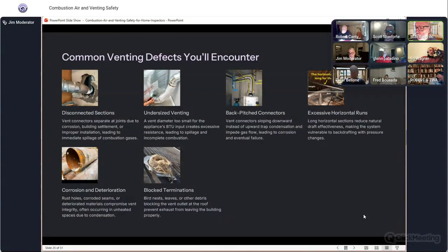And I've seen this, and people are getting water in their basement, water into the chimney, and they're looking all over the place. They're adjusting their grading, and they can't understand why water is coming in the house, because the chimney is too big, or the other way around, actually, too. The furnace is high efficiency, and the water heater is a very small appliance in that big chimney. So theoretically, we're oversized, and we're not getting that flue gas out of the chimney, and it's allowing the condensate, the moisture that we're releasing when we're burning the gas, to condense and come back down the chimney.